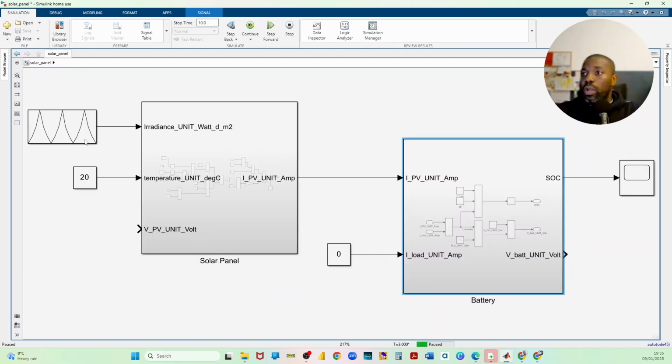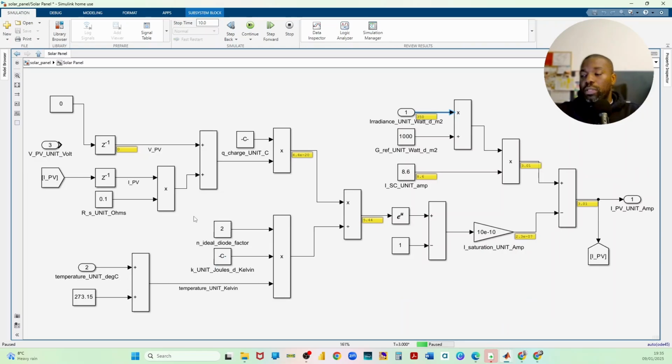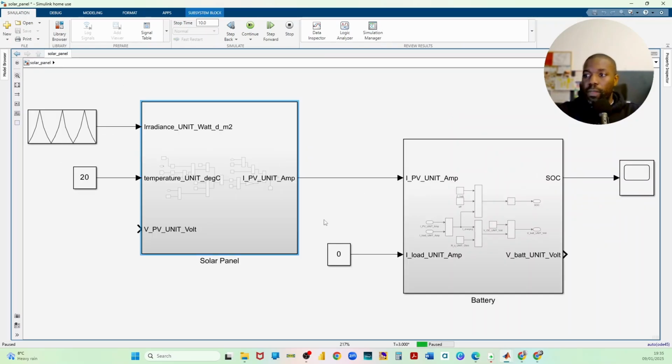Okay, so as a summary, what does that tell us? It tells us that not only are we able to model directly a very complex nonlinear system with an algebraic loop in Simulink, but the solar panel dynamics is directly dependent on the output for it to work. That is fundamental in understanding how a dynamic model works, and more importantly, the inputs that are required to give the very values that will be needed, specifically in this case, to charge a battery.